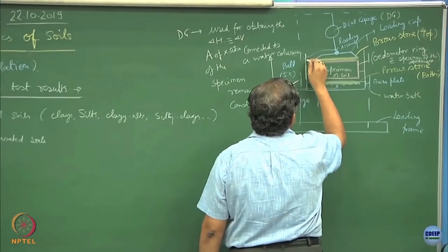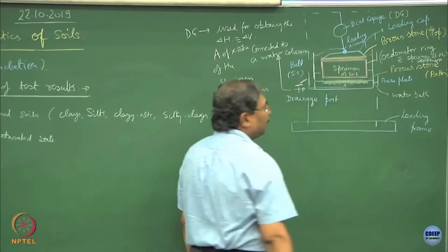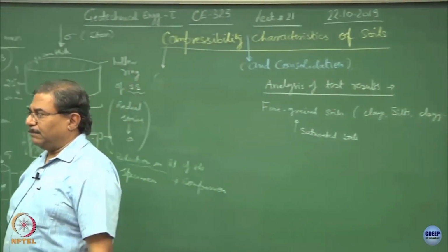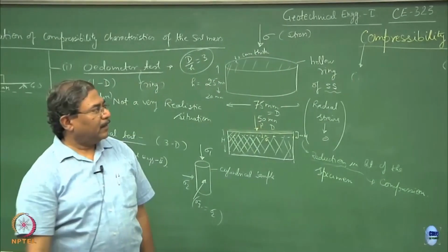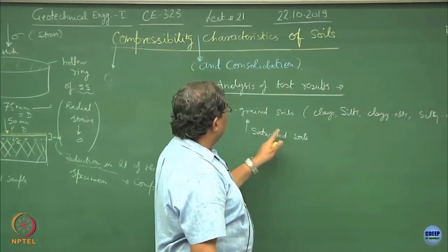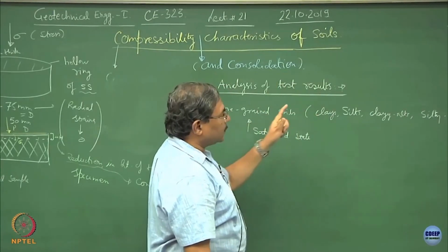So, the water can be maintained up to here. The specimen remains submerged in water all the time, and hence we ensure that we obtain the saturated state deformation and compressibility characteristics of fine grained soils in particular.